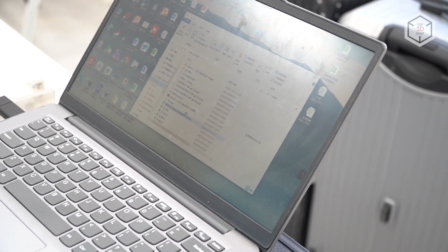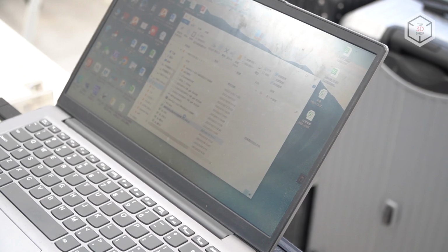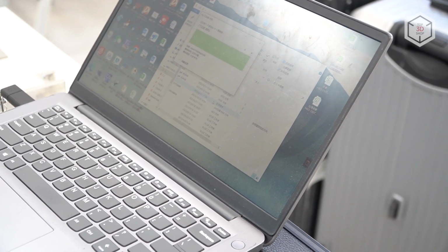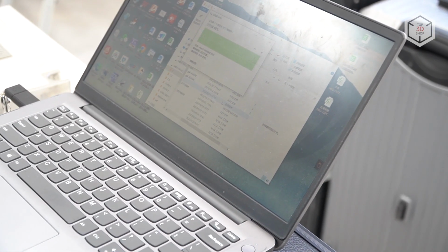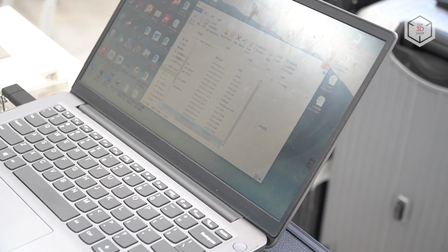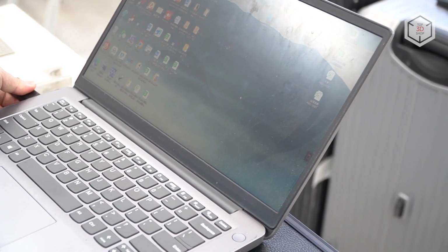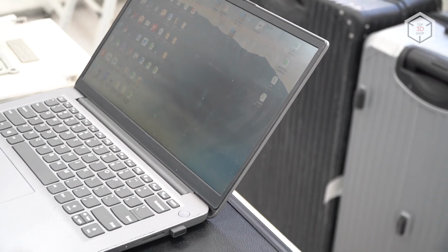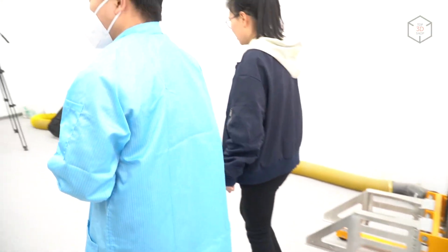So in total, you would normally expect to engage 3 software suites. The first one is your CAD software, for example, SolidWorks or AutoCAD. Then you would move it to Voxeldance Additive, where you set the supports and the positioning of the model. Then you transfer it to HBD Build Expert, where you're setting the path for the laser.